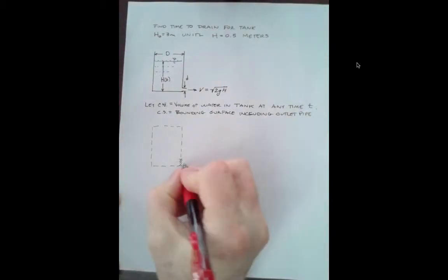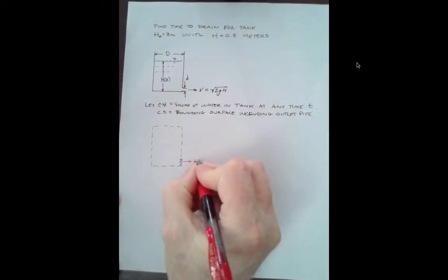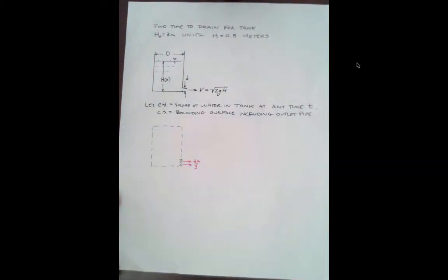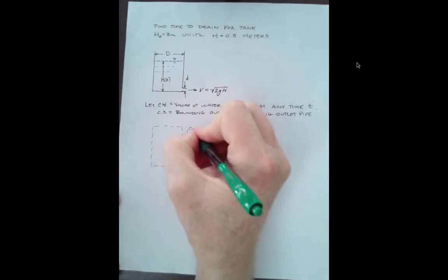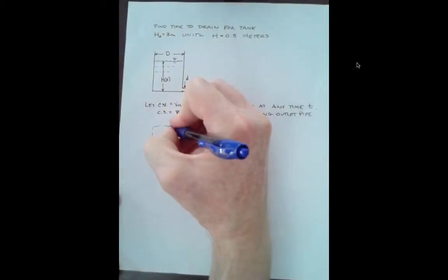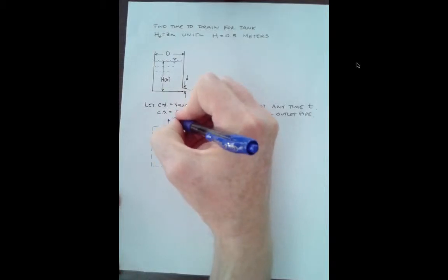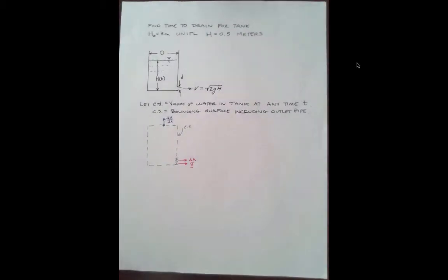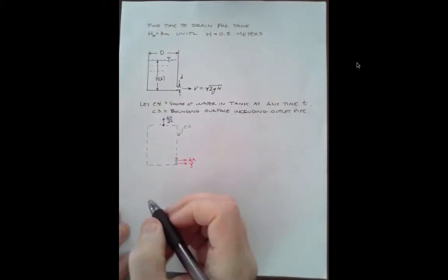Remember in class we said to indicate the outlet vector and the velocity vector. And that will help us get the signs correct. The green guy is our control surface, and in this case we will find it advantageous to keep track of the velocity of the free surface, dh/dt. Alright, there's our basic setup. Now we'll apply continuity and see what we learn.